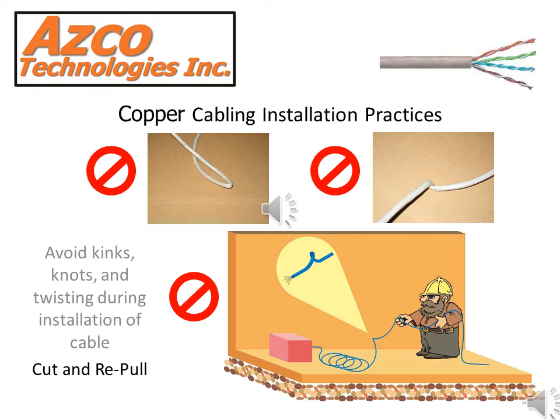Copper cabling installation practices. Cat5, Cat5e, Cat6 are cables often used for network cabling, telephone cabling, security cabling, and CCTV cabling. These cables are made to be balanced, and to avoid noise or crosstalk within the pairs of the cable, it's important to make sure that you treat the cable with care when installing it. Avoiding kinks, knots, and twisting during installation of cable is important. If you do have any of these, cut and re-pull the cable.